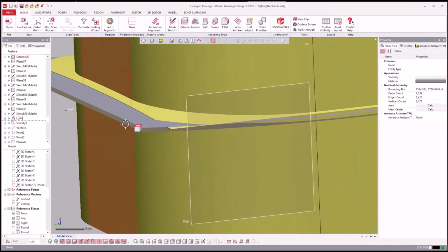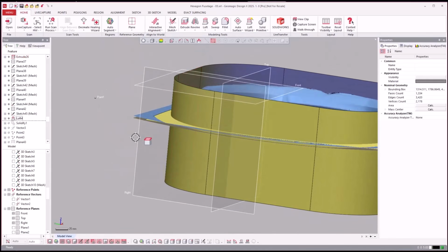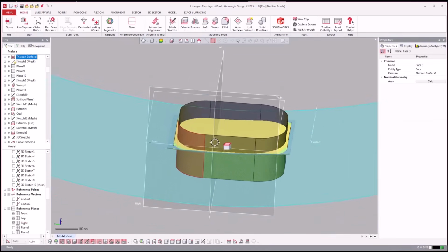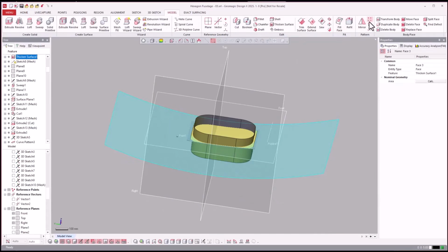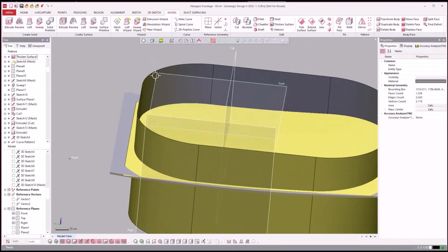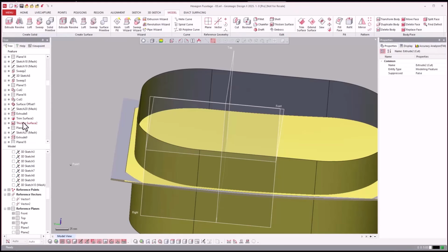One thing that I did on the bottom here is we grabbed that big surface that we created at the beginning, and we did the typical offset 0. So what that means is we fit a surface to the top, we did offset 0 for the bottom, and then we have this for the sides.